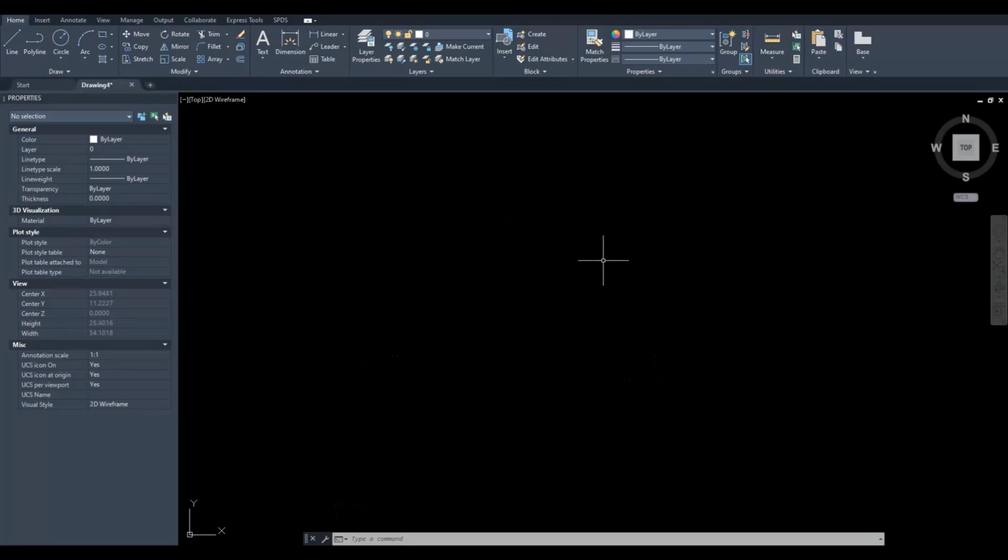So we're going to open up a new drawing file. This is perhaps the drawing file or the drawing project you've been working on. So you made your drafts and everything. Now you want to plot your drawings on the paper space. So the first thing we want to do is to prepare the information for the drawing. This could be done prior when you're beginning with the main drawing. So all of the plotting is done in the layout tabs.